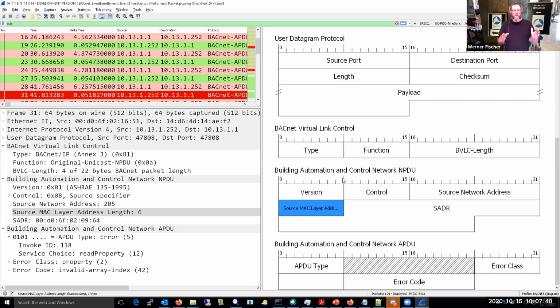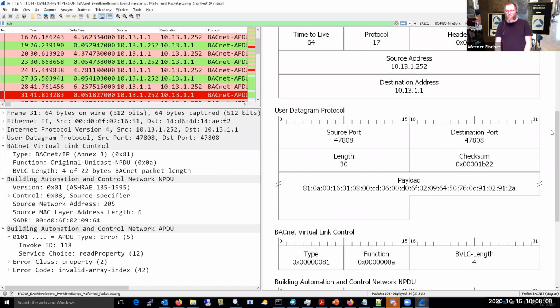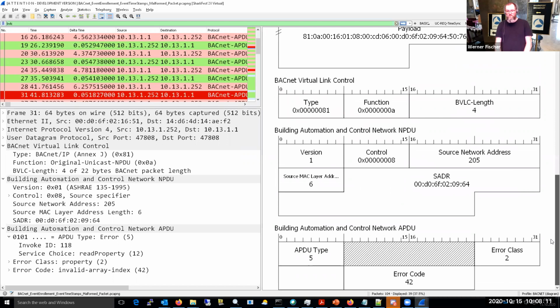An Ethernet MAC address has 6 bytes or 48 bits. In BACnet, they also use a MAC layer address, but with a value of 8 bits. You see it on ARCNET, for example, and you see it on master-slave token passing. Another feature Gerald mentioned also: right-click and show field values. And all these values are put into this diagram.